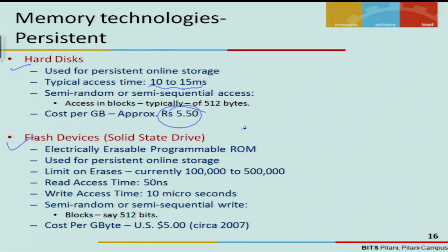And solid state drives are basically a form of electrically erasable programmable ROM, so EEPROM, and it's used for persistent online storage. The number of erases is limited, as per the current technology somewhere near 100,000 to 500,000, depending on the vendor. And read access time also depends upon how the memory has been constructed.